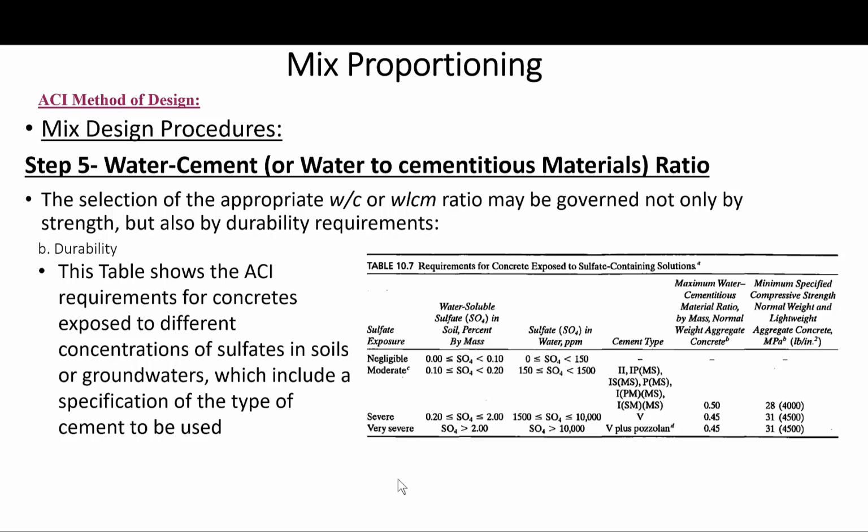In addition, as far as the durability requirements, this table shows the ACI requirements for concretes exposed to different concentrations of sulfates in soils or groundwater, which include a specification of the type of cement to be used, as you can see here. So these are good references to use in cases of various conditions of exposure.